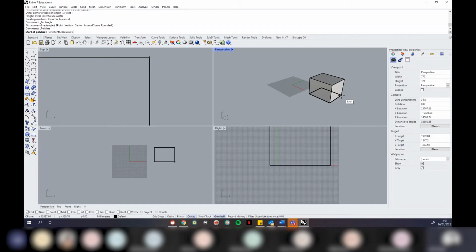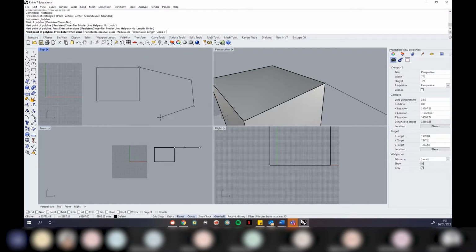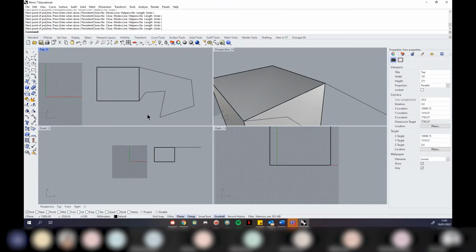So essentially, if I wanted to draw, for instance, a roof on something, I could click over here to define that I'm drawing on this plane. And then when I enable planar, this basically conforms it to snap to that plane, so it will stay at that set elevation.